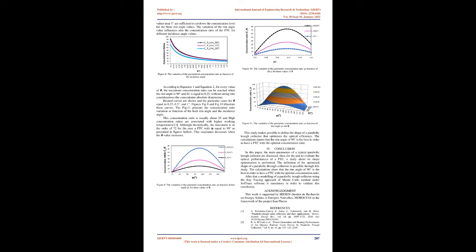G. Energy balance in a PTC. There are three sources of energy loss in a typical PTC, and are presented as follows. Optical losses due to mirror reflectivity, intercept factor, glass transmissivity, and absorptance of the receiver tube when the solar radiation incidence angle is equal to 0 degrees. Additional optical and geometrical losses due to an incidence angle greater than 0 degrees. These additional losses do not exist when the incident angle is equal to 0 degrees because the modifier equals 1.